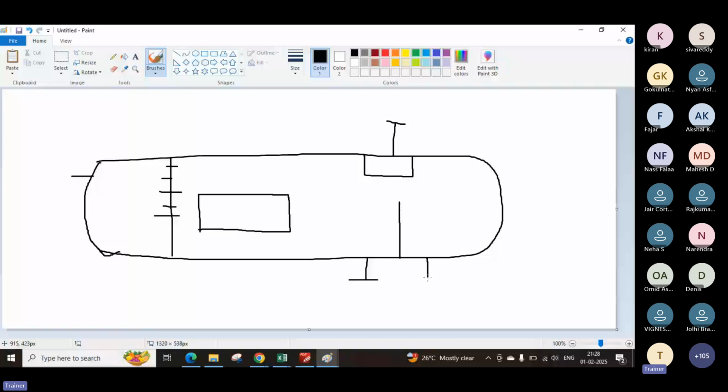The calming baffle is there to regularize the movement of the liquid and to lower the fluctuations so that we can have quick separation. So when we have a three-phase separator and the vane pack is arranged like this, the fluid flows between this section, and during its movement it keeps touching the surface and changing its direction. Small particles of the light oil or light density fluid coalesce together, and when they come back, they directly try to move upward, and the heavier particles try to go downward.